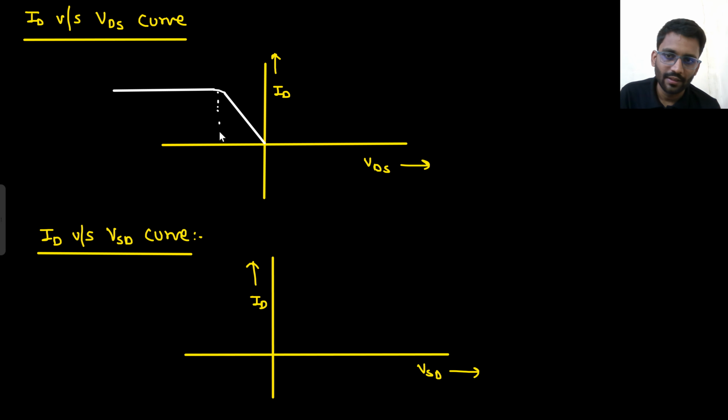Tell me. That will be VGS minus mod of VTP. Because VGS is also negative. Source is 0, VG is negative. So negative, no, not mod of VTP. It should be mod of VTP or only VTP? Tell me, mod of VTP or only VTP? VSG minus VTP. VSG is already higher. Yeah, it should be directly VTP, not mod of VTP.